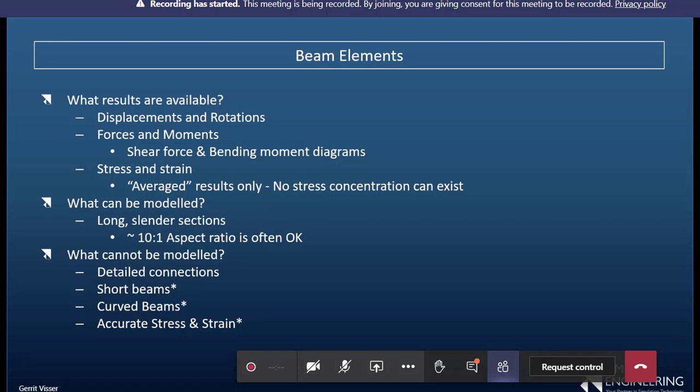Just one comment. If I look at the previous slide, we had that example of the shear stress being the force over the area, the shear force over the cross-sectional area. That does not exist in real life. It's impossible to get to that stress state. And the reason for that, if you remember correctly, is that the shear stress on the top and the bottom of the beam has to be zero, because of the way that the stress tensor works. So that means we end up with that hopefully familiar parabolic stress distribution shape through the thickness.